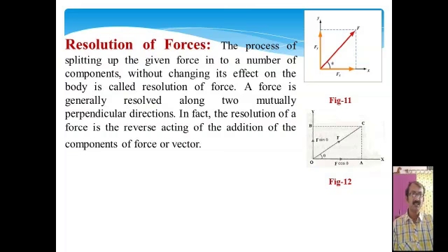In fact, the resolution of a force is the reverse of the addition of the components of force or vector. So in figure 11, it is clear that this is the force F. This force can be represented in the x direction, that is Fx, and in the y direction, that is Fy. In figure 12, it is also clear that this Fx is nothing but F cos theta, and Fy is F sin theta, where theta is the angle between F and the horizontal axis x.